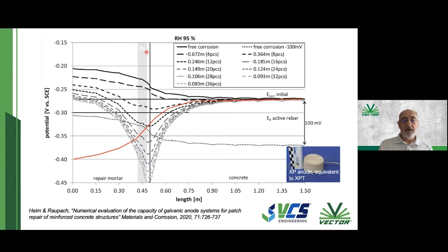Originally, you've got an area here in which the steel is corroding. That's the center of the slab. That's the edge of the slab over here. This area is assumed to have a lower level of chloride, and this has a high level of chloride, which induces corrosion in the center. And if you look at the potential map of that, then it's that red line.